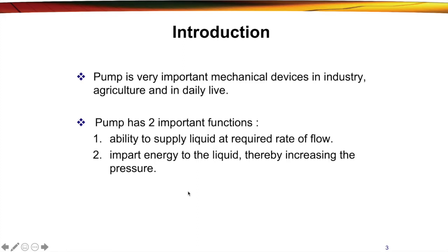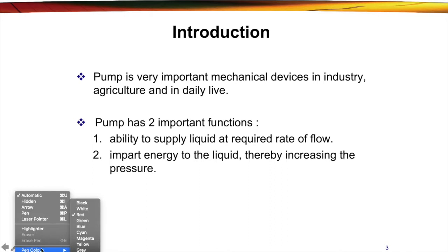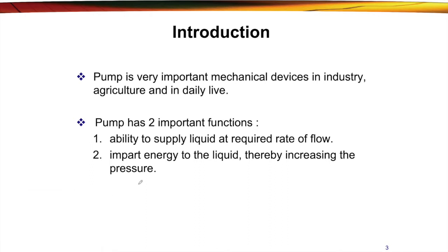So as we know that previously we already calculated the major and minor losses. So let's say we have these types of configuration. For example, we want to transfer from A to B. So we have two minor losses here, and then we calculate the major losses from the Bernoulli's equation.